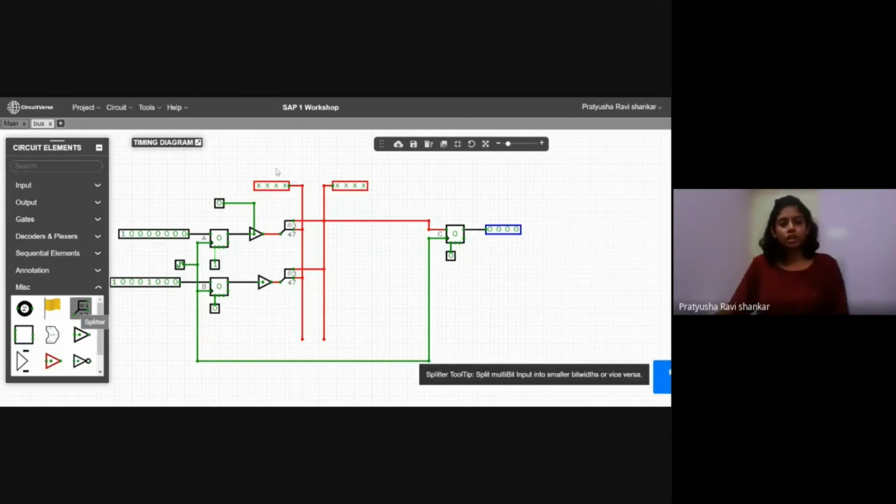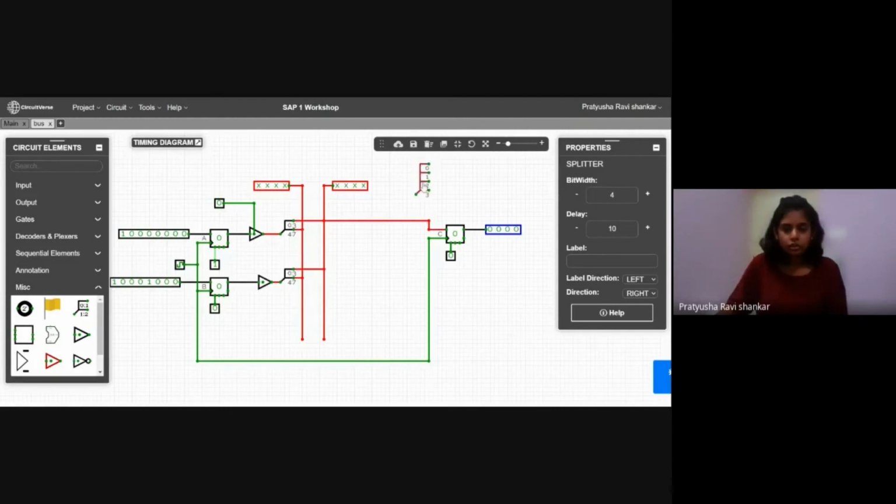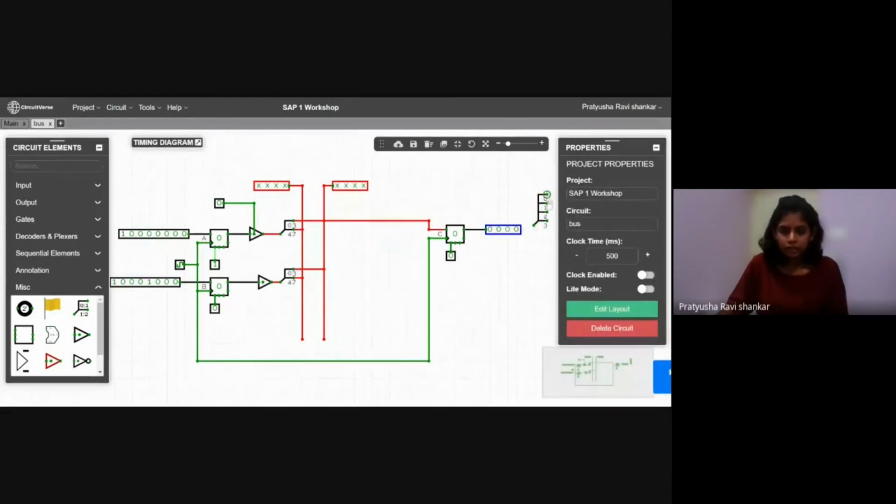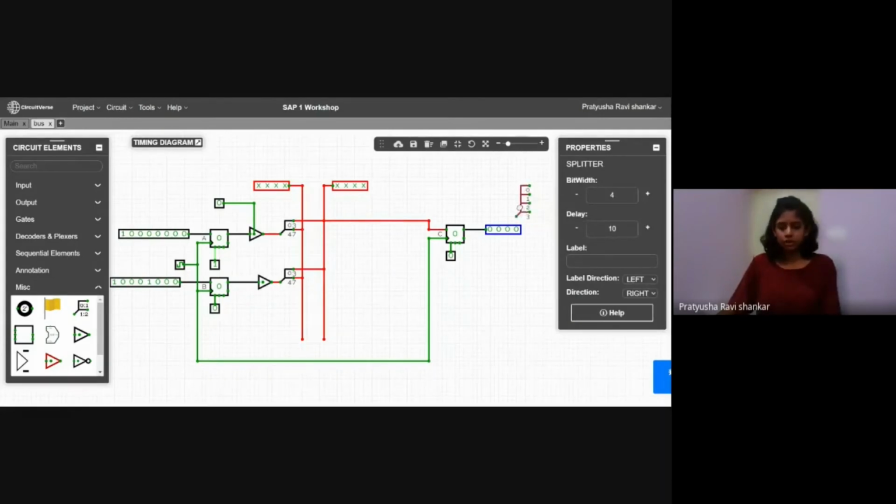So let's say your bit width is 4. The input you are getting here is 4-bit, and you want each bit out of this separately. So what you'll do is 1, 1, 1, and 1. So voila. You can give, suppose, a 4-bit input here, and you'll have your LSB here and MSB here in the same order. So you could play with this ratio and see how it works for you. I guess you understood, Amrita. Yeah, awesome then.